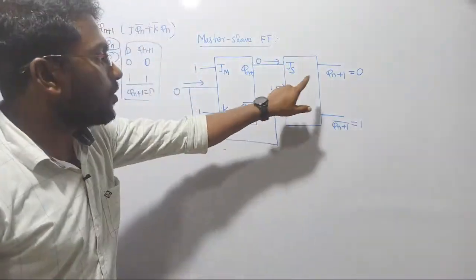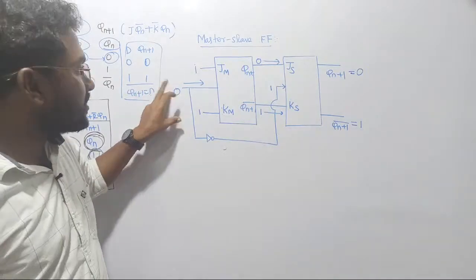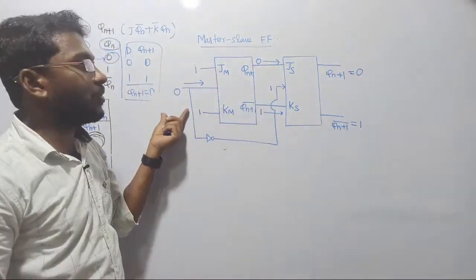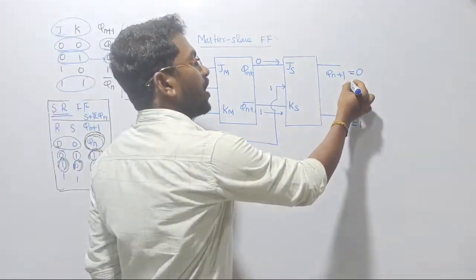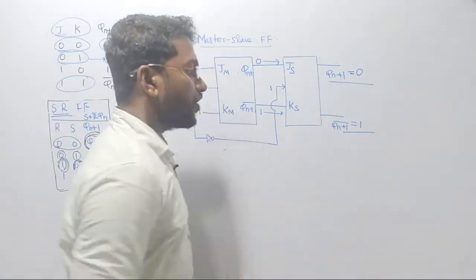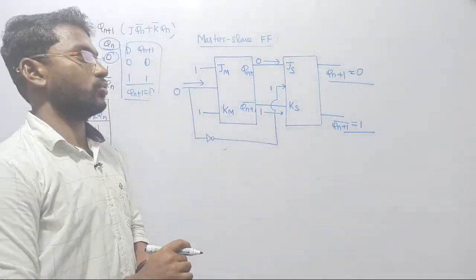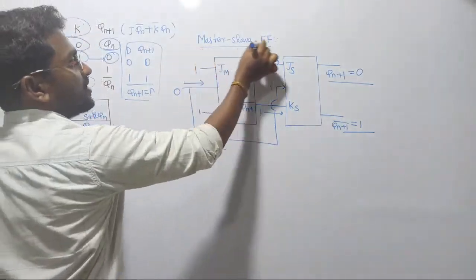It will be fixed now, right? See there, it will be controlled with the help of clock pulse. It is hardly depending on the clock pulse only, right? So only depending on the clock pulse, right? So with the help of clock pulse, automatically you can fix the state of this circuit without facing that race around condition issue. Clear? That is all about master slave flip-flop.